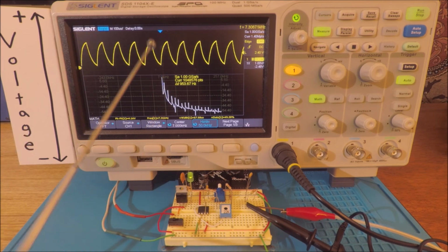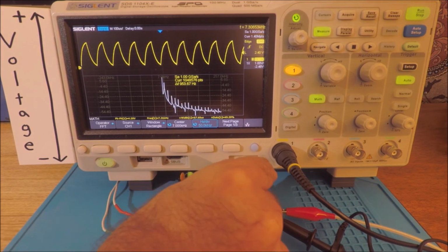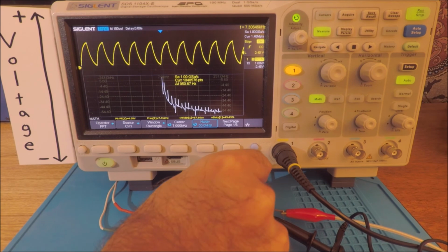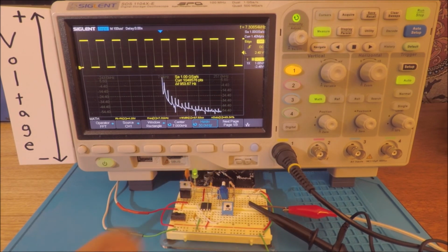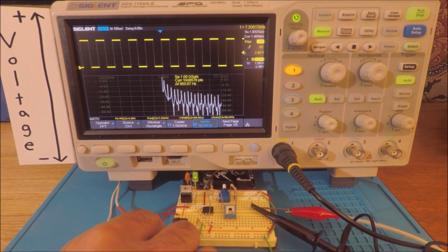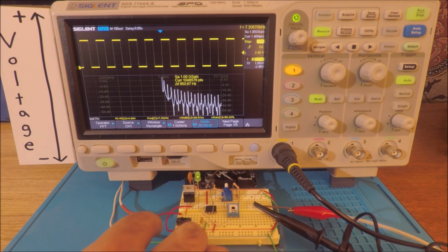The two are related. There's a nice little trick you can do with the digital storage oscilloscope, and I'll demonstrate that by removing our capacitor first. And so here we can see that we've restored the higher order harmonics by removing that low pass filter, and now we have our square wave back in the time domain.